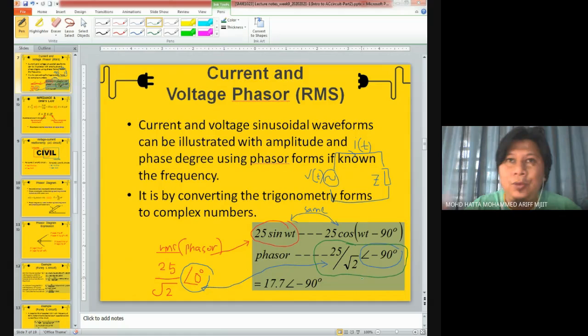If you use voltage in a cosine form, then in order to write i(t) later on, I can be calculated using V divided by Z, and you can write i(t) based on the current magnitude and the angle found here.